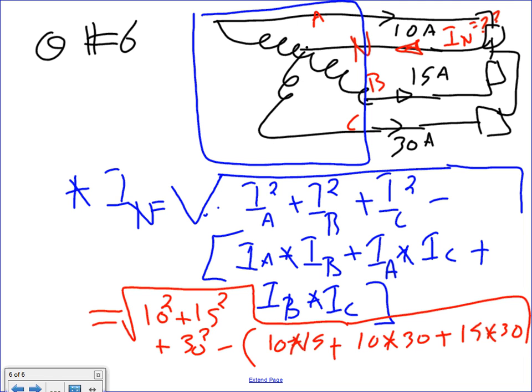And all you have to do is do the math. The hardest thing is getting the math right if you're not good with that. It should be 18 amps. Anybody come up with something different? Should be 18 amps. Not even close? 43? Okay. Here's a mistake a lot of people make. You have to add all these, then subtract the total.